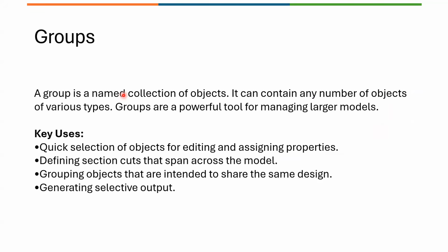And then we'll be using groups. The group is another feature where it is going to help us in the modeling itself by selecting objects by groups. For example, we want to assign the loads or change properties. So groups will, because we have typical members in the steel structures, like all the moment resisting frames, all the secondary beams, like that you can group and then use them for all editing, assignment, etc. And you can also use them to get section cuts.